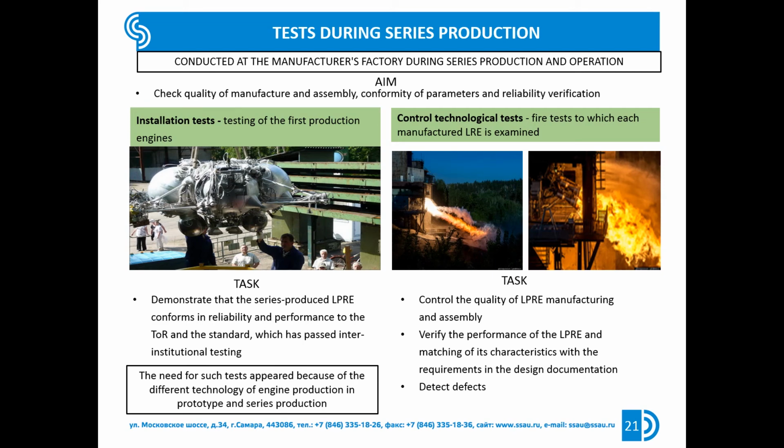Based on the result of the control and technological tests, the LPRE is also adjusted to the specified mode of operation if necessary. The duration of control technological tests is usually a few tenths of seconds. During these tests, the engine can be operated in several modes in terms of combustion chamber pressure and fuel component ratios. The duration of operation in each mode shall not be shorter than the time required to change and stabilize the thermal, vibration and other types of loads on the LPRE components.